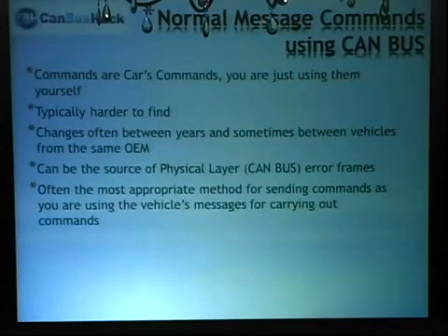This is data that's just normally going out there. And the problem with CAN bus is, if you have a controller that's sending that message, but you want to send it instead, that controller is not going to stop sending that message just because you want to send it. So you have to find really creative, intuitive ways to make that message disappear as best as possible, or to send your message immediately after it so that you can send your own version of it.